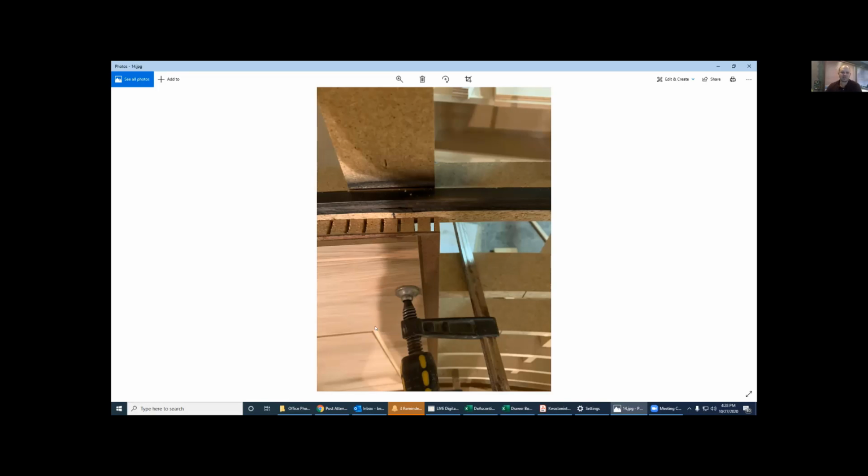The challenge here, from a geometry standpoint, was that the radius of the wall and the back of the kerf core is a different radius than the back of the face material, and a different radius than the face of that material, and a different radius than the polished metal band. So when everything was laying flat and you could measure it, nothing measured right. But when you bent the sandwich around the radius, everything lined up. Figuring out how to cut the metal bands so that when they were on the radius, they dropped into the groove was the fun part.